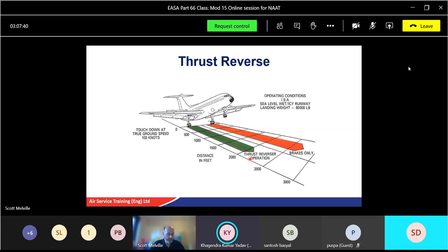Vaporizing, yeah. And what was a common name given to the vaporizer, because it looked like something? Hockey stick. Yeah, hockey stick. And what was special about the vaporizer burner compared to an atomizer? It tends to face forward. Yeah, and what happens to the fuel before it goes to the vaporizer? Yeah, preheats it. We preheat the fuel so it comes out like steam. Okay. Good.